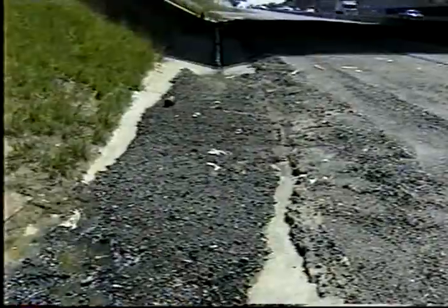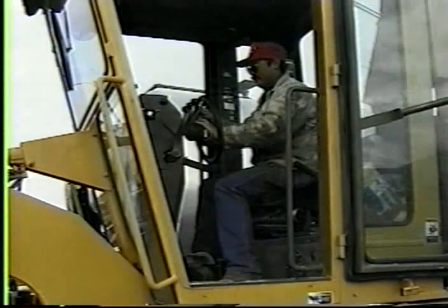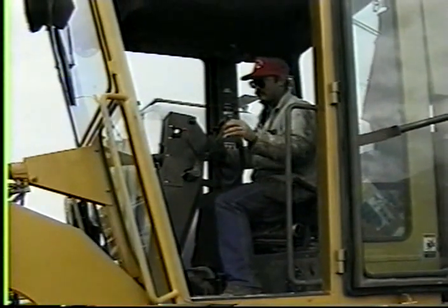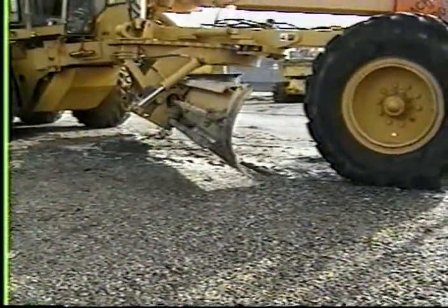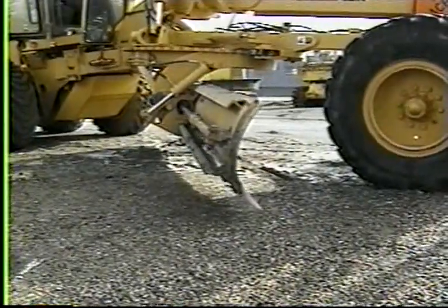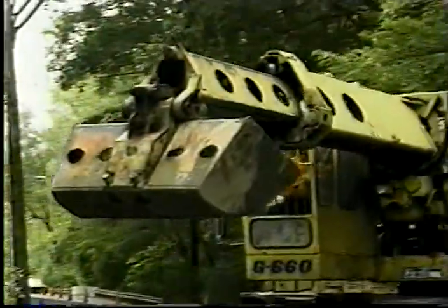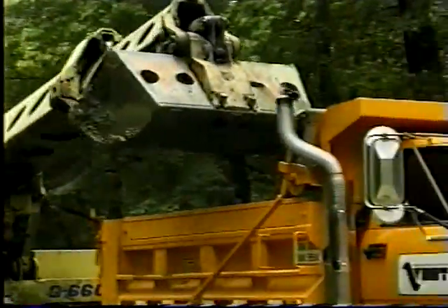Ditches must be kept free of silt, debris, or any other material that restricts the flow of water. The flow lines of unlined roadside ditches are maintained by motorized equipment supplemented with handwork. Large roadside ditches are sometimes located at an elevation well below the roadway and are not accessible to a motor grader. These may be reached with a truck-mounted hydraulic excavator operated from the shoulder.